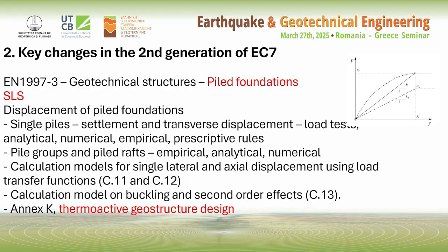For SLS, here again there are some very useful additions. For the displacement of piled foundations for single piles, there are such aspects as settlement and transverse displacement, load curves, also for pile groups and pile rafts by using different kinds of methods. There are calculation models for single lateral and axial displacement using load transfer functions, and also a calculation model for buckling of piles for very slender piles and second order effects.